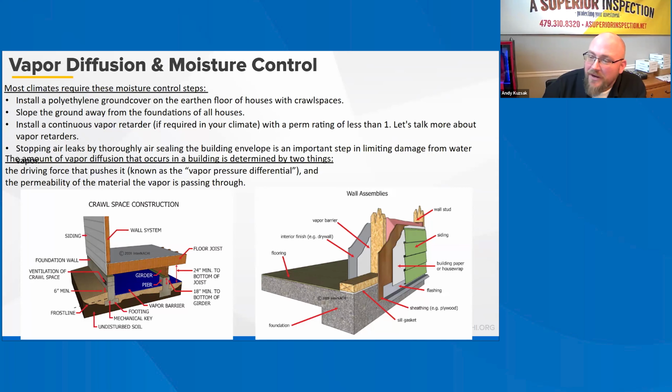In most North American climates, vapor barriers, or more accurately, vapor diffusion retarders, should be part of a moisture control strategy for a home. A vapor diffusion retarder is a material that reduces the rate at which vapor can move through a material. The older term vapor barrier is still used, even though vapor diffusion retarder is more accurate. It is a myth that installing vapor diffusion retarders is the most important step for controlling moisture in the walls.